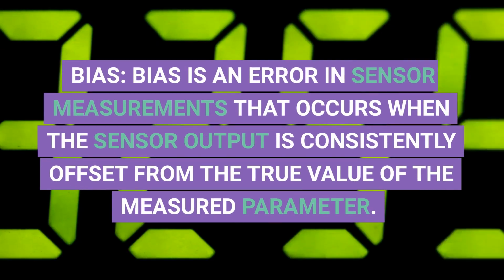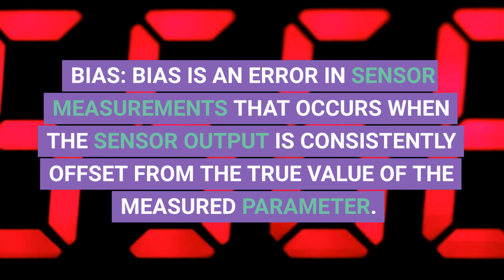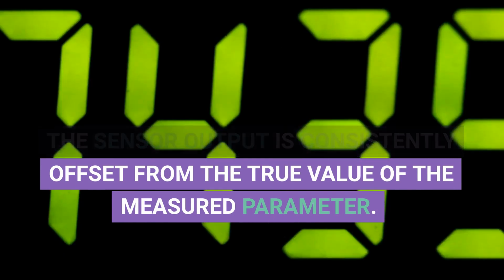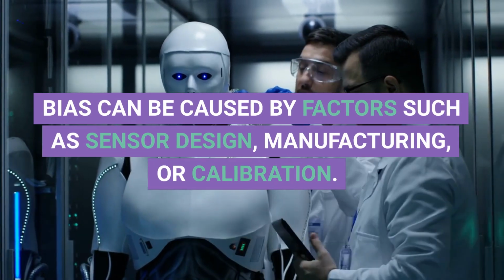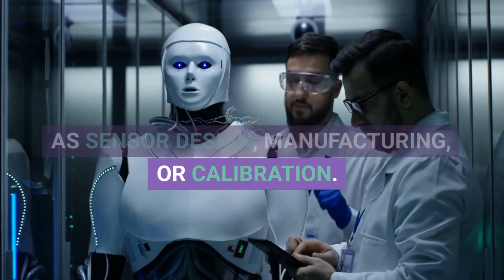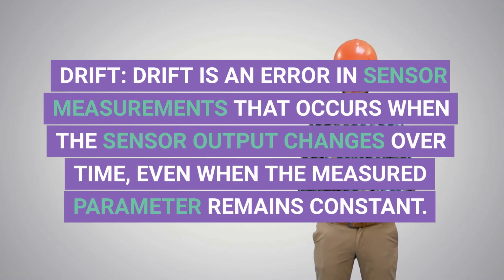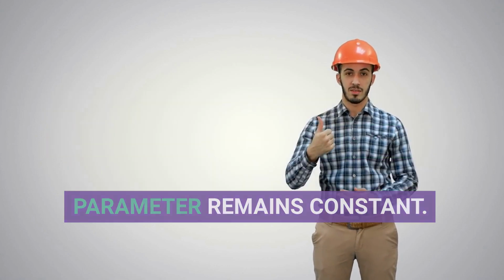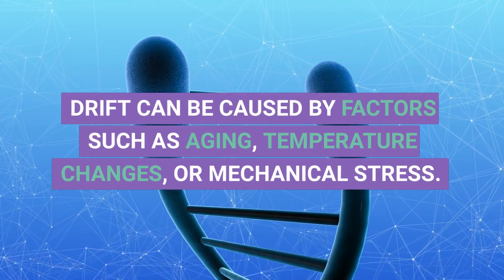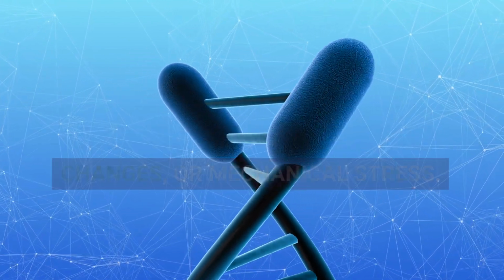Bias. Bias is an error in sensor measurements that occurs when the sensor output is consistently offset from the true value of the measured parameter. Bias can be caused by factors such as sensor design, manufacturing, or calibration. Drift. Drift is an error in sensor measurements that occurs when the sensor output changes over time, even when the measured parameter remains constant. Drift can be caused by factors such as aging, temperature changes, or mechanical stress.